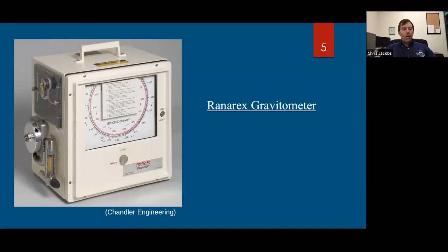All right, now moving along, this is the selector valve here. So there are 3 positions on this selector valve. There is a 0 position. There is an HG for gases that are heavier than air. An LG position for gases that are lighter than air.